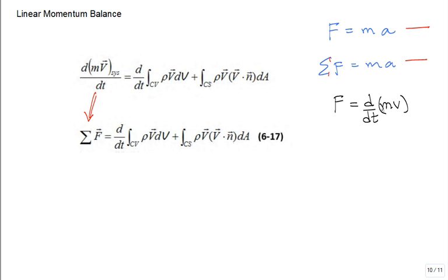But right here, it does work. If I have a system where the mass is not changing with respect to time, guess what? That can come out. But a lot of times they just leave it inside. Okay, there you go. So that's why you can replace it right here for the linear momentum. The sum of the forces change the linear momentum of the system, of our closed mass system. And then if you want to put it into a control volume, you have this time rate of change of the mass in a fixed region of space, control volume, and then the flow over the boundary.